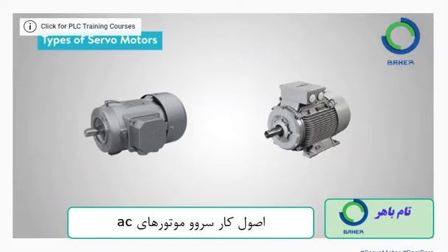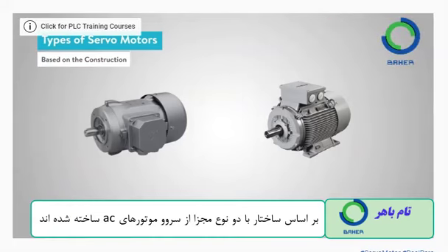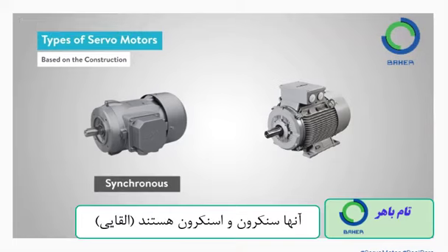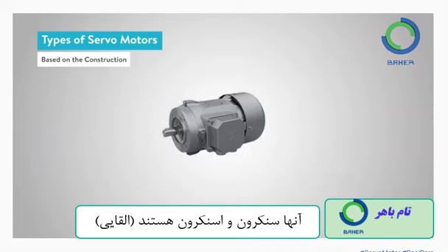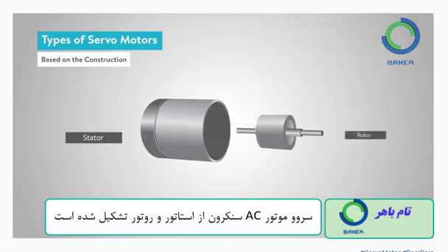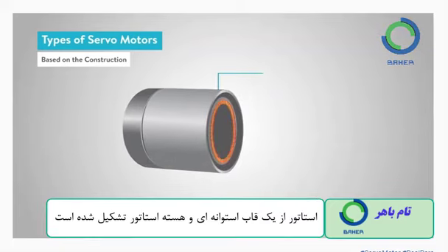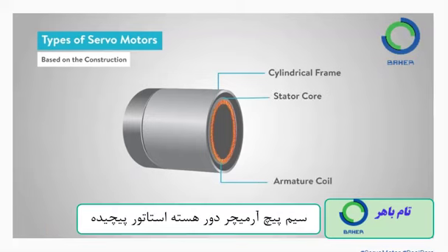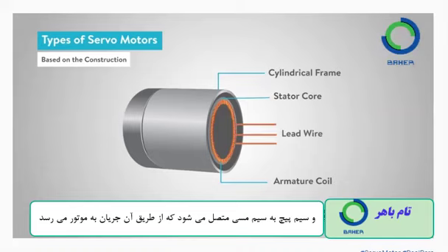The working principles of an AC servo motor are based on the construction with two distinct types of AC servo motors. They are synchronous and asynchronous, or induction. The synchronous AC servo motor consists of a stator and rotor. The stator consists of a cylindrical frame and stator core. The armature coil wound around the stator core, and the coil is connected to a lead wire through which current is provided to the motor.